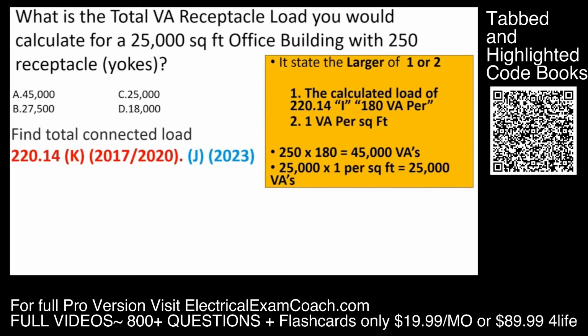Part 2 says we need to take it at 1 VA per square foot. So we take 25,000 square feet multiplied by 1. That equals 25,000 VAs. That portion of the calculation we're done, but that first part, there is a demand factor that applies to it. So we check for demand factors.